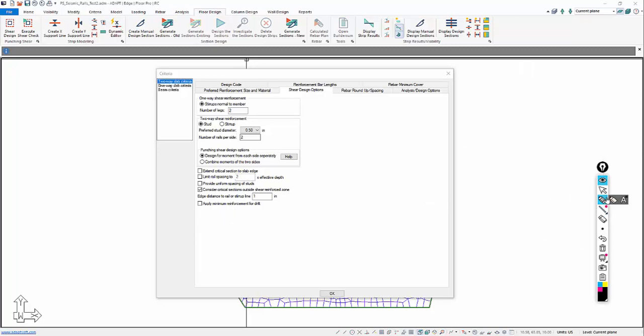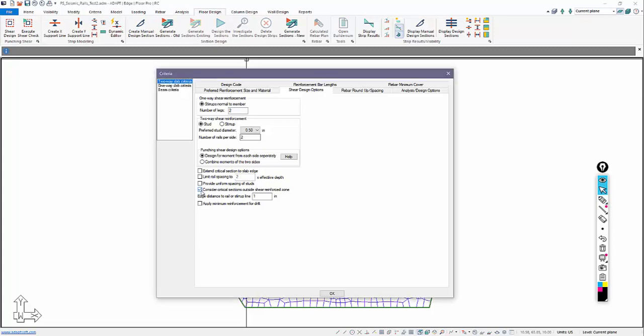The next improvement is related to slab and column connections for joints that may not be part of the lateral system. There's a requirement in high seismic design categories D, E, and F where you need slab shear reinforcement necessary to provide greater than or equal to 3.5√f'c, for a distance 4 times the slab thickness to each side of the column.